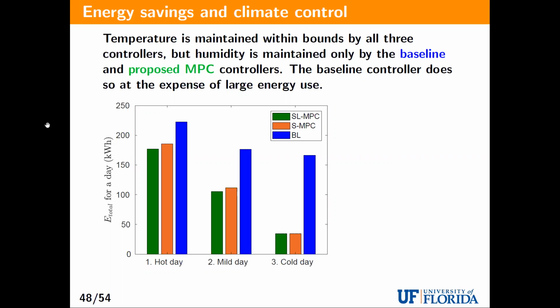How is the humidity-based controller beating the sensible only if you're trying to take care of a whole other variable? So as you can see, it's not always beating the other MPC controller. It seems like it should be losing in terms of energy use. It might actually lose in California, but in Florida, because humidity is such a big concern, right?